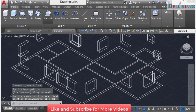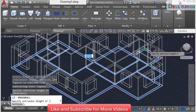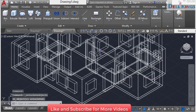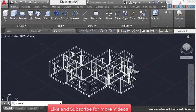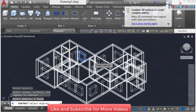So now repeat press pull again at this point, and we can now select this point or the inside of this building. Alright, so we can now press pull and give it a height of 3000 millimeters and press enter, and then press enter. So now we are going to end object isolation. Next, we are going to subtract the doors and the windows. So zoom in again and subtract the doors and the windows from the main building. So select subtract and click on the main building and press enter. So you can now select all the doors and the windows.